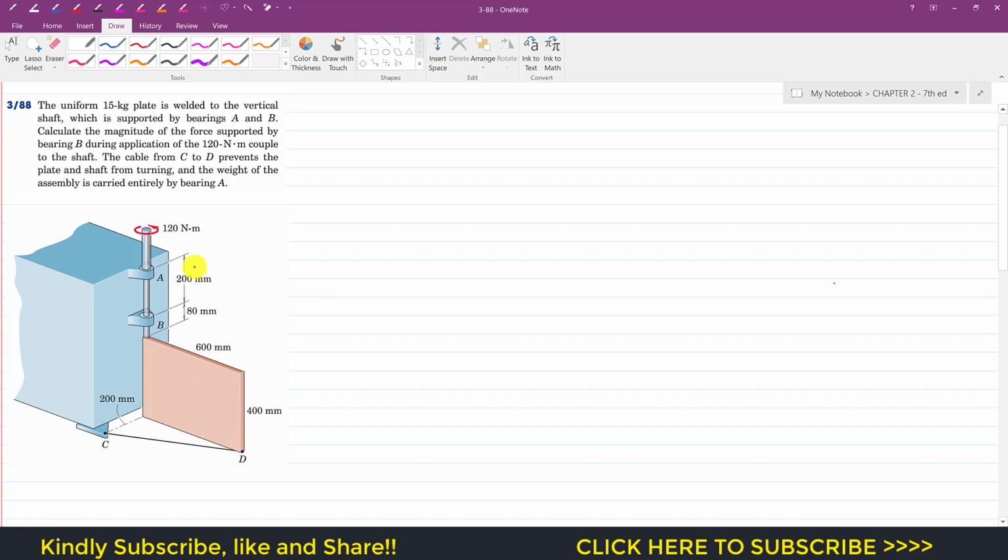So first of all, we have to define our reference coordinate system. Let's say my x-axis is acting from the shaft in the outward direction like this. Let's say this is our x-axis, and let's say my origin is at point A. Then our y-axis is in this direction, and the z-axis is along the shaft, acting in the upward direction. So now this means that the shaft is along the z-axis.